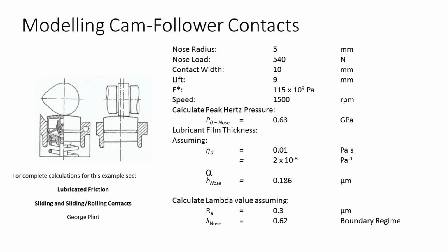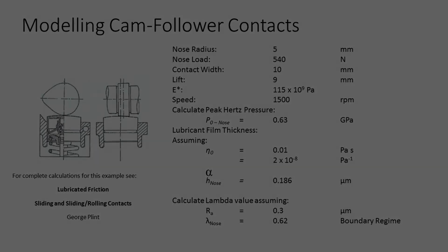In this example, we have a quite complicated wedge-on-sphere geometry designed to promote rotation of the bucket follower, thus producing a circular wear track. For our benchmark calculations, we use a simplified geometry comprising a cylinder on flat with a 10mm wide contact width. Only by doing the appropriate analysis can we establish the lubrication regime under which our component is running, hence determine the test conditions in an appropriate model system in which to generate relevant and meaningful wear or failure data.